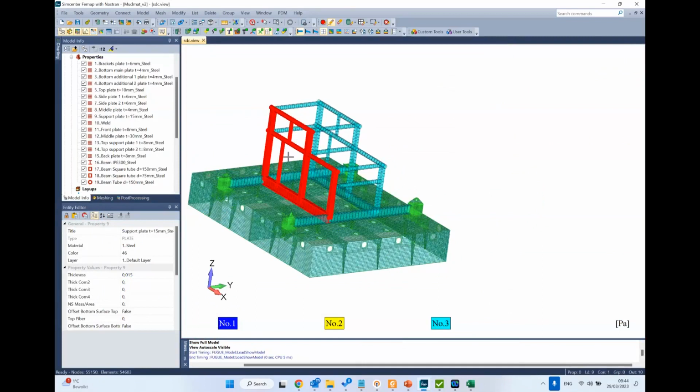It is convenient for big lattice structures where you need to report the results. You can report them by section, that is frame 1, frame 2, or section 1, section 2, section 3. So it's basically beam members grouped into global planes or custom planes for ease of reporting and result presentation. Thanks. Any more questions?